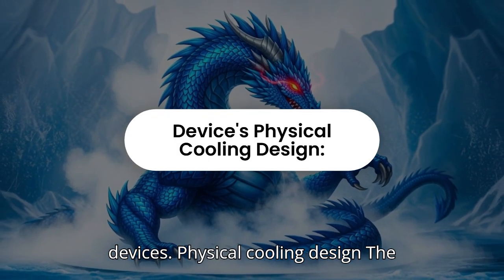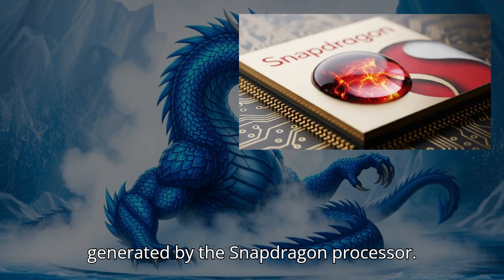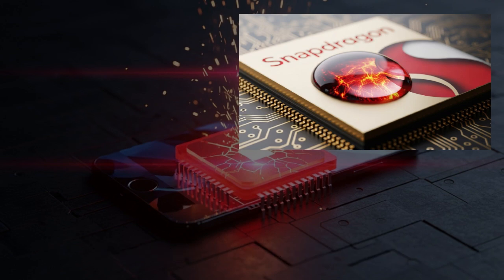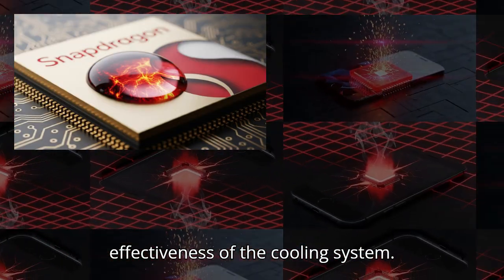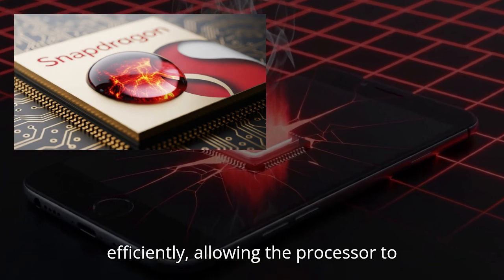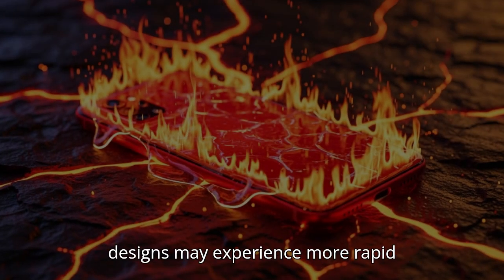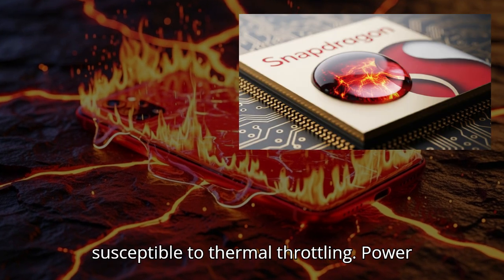Device's physical cooling design. The physical design of the device plays a crucial role in dissipating the heat generated by the Snapdragon processor. Factors such as the presence of heat pipes, vapor chambers, thermal paste, and the overall airflow within the device all contribute to the effectiveness of the cooling system. Devices with more sophisticated cooling systems can dissipate heat more efficiently, allowing the processor to maintain higher performance levels for longer periods. Devices with poor cooling designs may experience more rapid temperature increases and be more susceptible to thermal throttling.